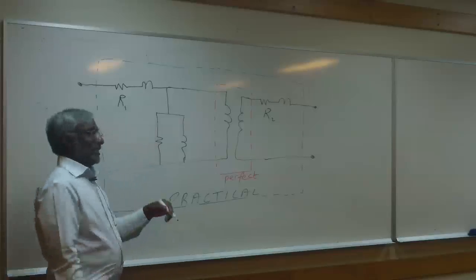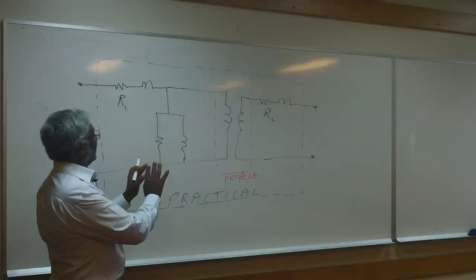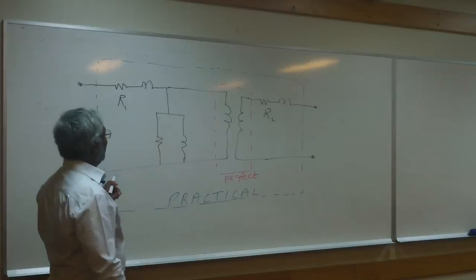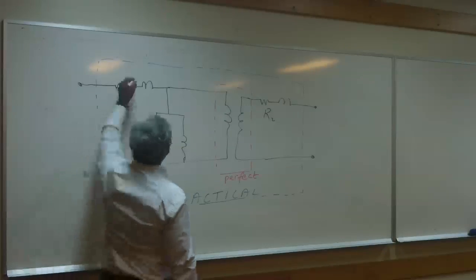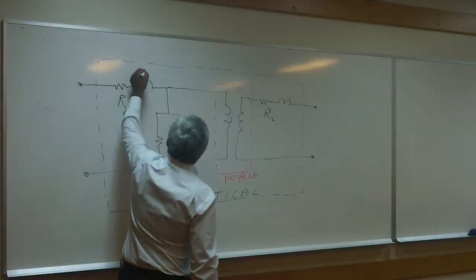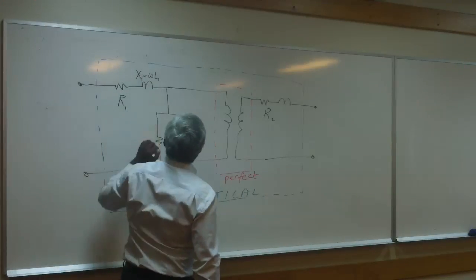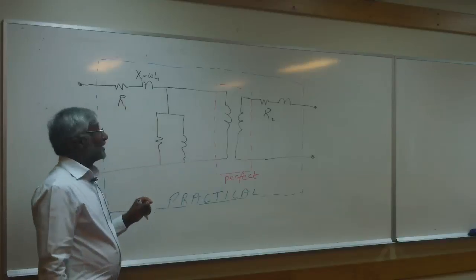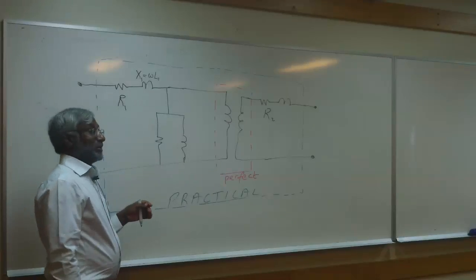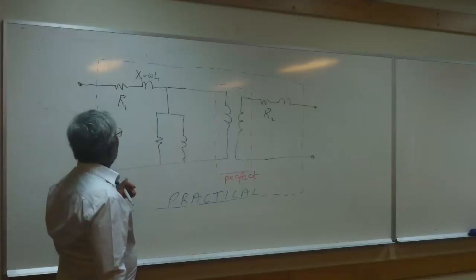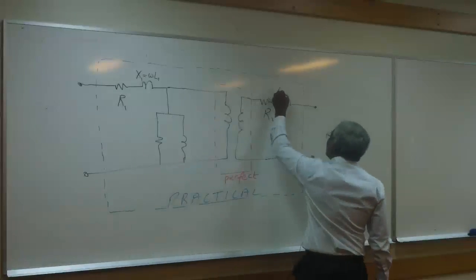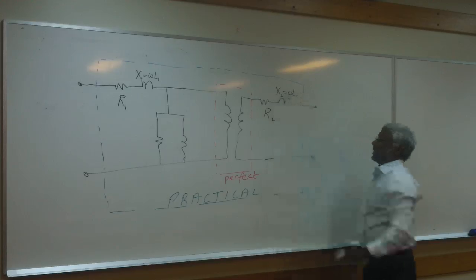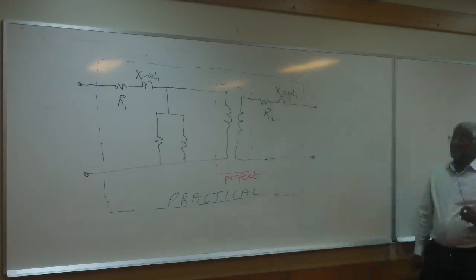Watch my other video that I'll put on later, so you would be able to relate X1 to L1, but it's very simple, of course. You would have to remember that X1 equals omega L1, where L1 is the leakage inductance, which is associated with leakage flux. Similar on the other side. So that's the secondary side leakage flux, and from memory, we did talk about this last time.